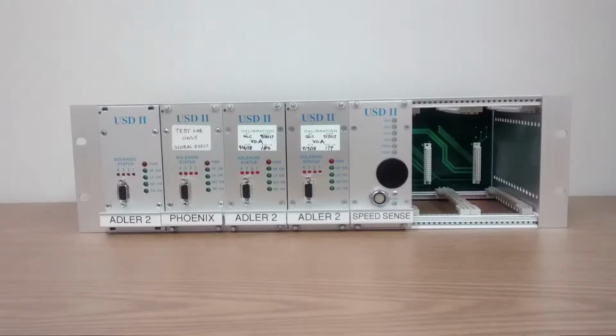To control more than 4 solenoids, users just need to add additional modules into the same rack. The types of multiple modules simultaneously operated within a USD-II rack may be mixed and matched according to test needs. In fact, multiple racks may be daisy-chained together if more than 7 modules are required. However, this is seldom necessary nowadays, as recent modules drive 4 solenoids each, unlike earlier USD-II modules that control just 1 solenoid per module.